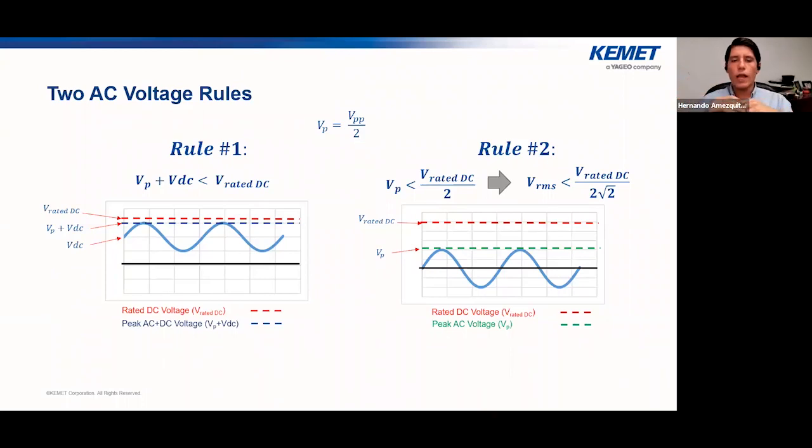So you have to consider the peak AC voltage that you're having, because it is not equivalent to say the AC voltage to the DC voltage. So there is a safe room of operation, and that's why the recommendation of considering 2x the peak voltage, basically.